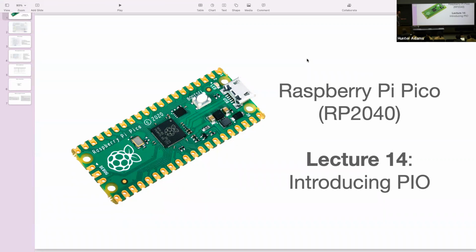One is to remember that we're keeping track of our Boid position and velocity using fixed point. And there's a section of the algorithm which you're all asked to implement this week, which is speed checking, which involves a division by the present speed of the Boid. You're renormalizing by the Boid's existing speed. Remember that that division requires a fixed point division, for which there will be a macro at the top of your demo code. So a relatively common error that I'm seeing is to use the divide symbol instead of the fixed point macro for division. And the consequence of that is, I think, stationary Boids. I think that's the bug that we see.